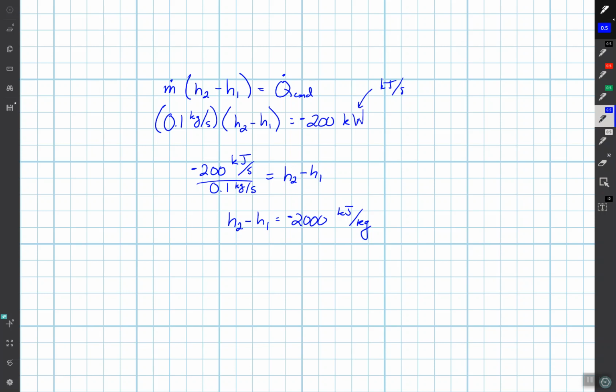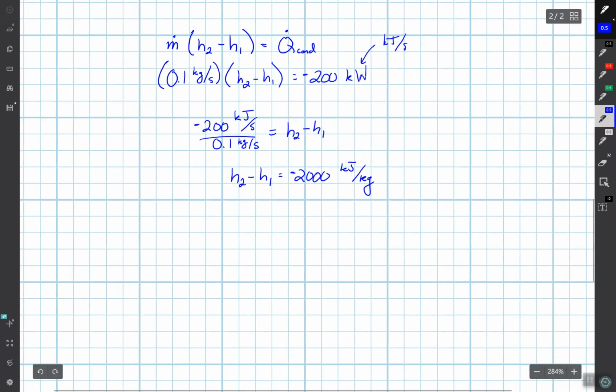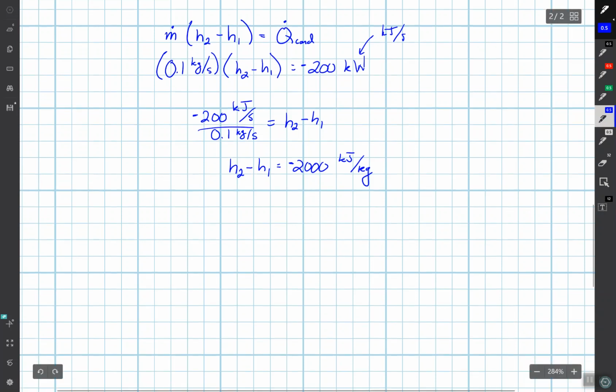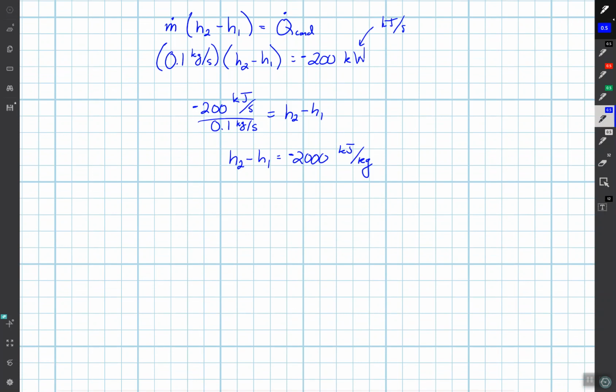Part of that gives me an opportunity to talk about the sign and make sure that we have the sign correct. You're always thinking the sign convention that you're using is a steam engine, where we would put heat in and get work out. In this case, we're taking heat out, so that means it's a negative. It's backwards to how a steam engine works. Steam engines, the birthplace of thermodynamics. So we're going to use that as our sign convention here.